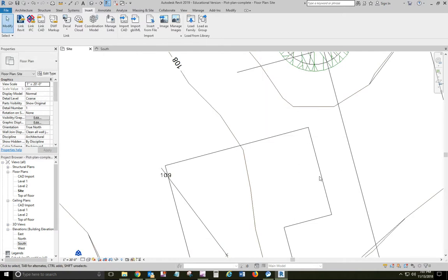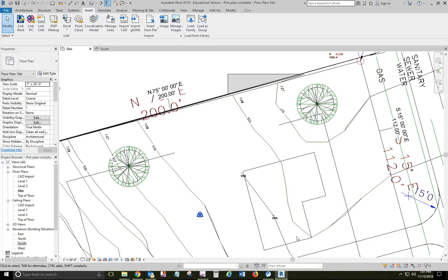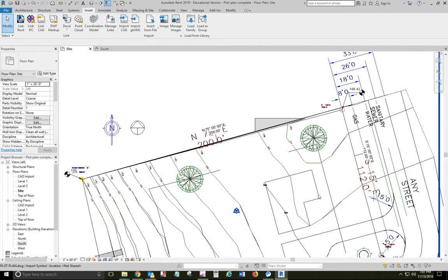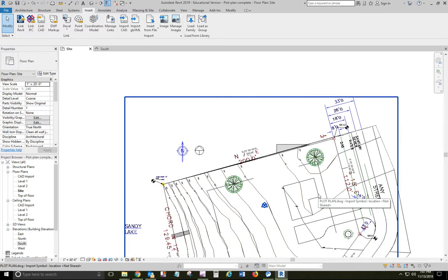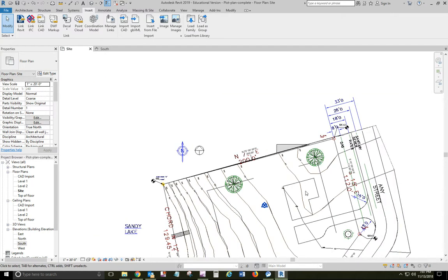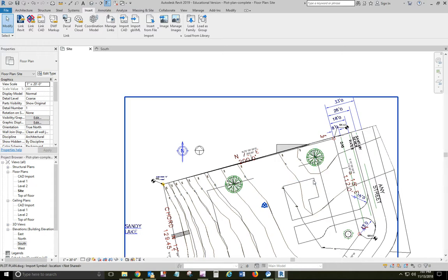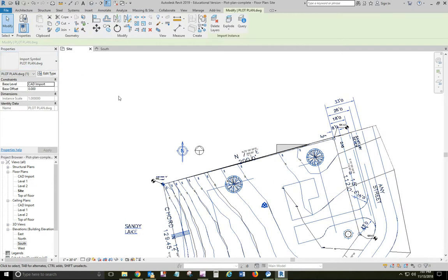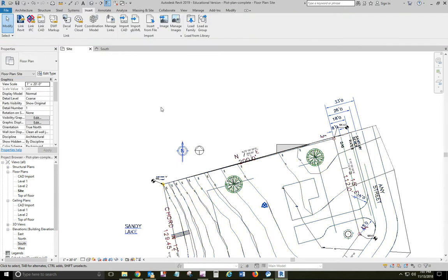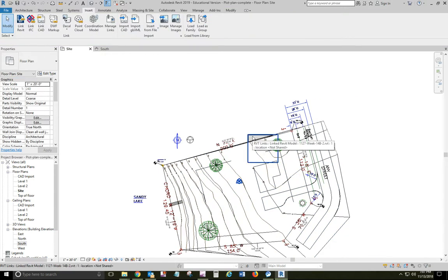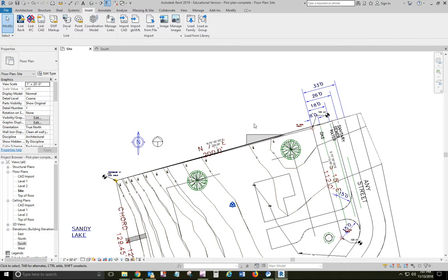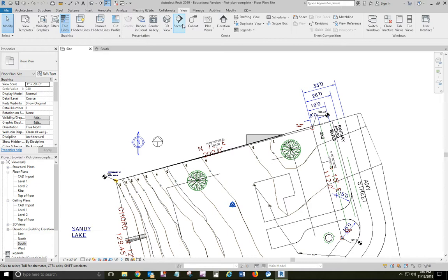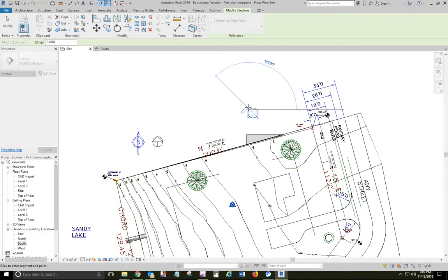of my building layout. This is the layout of the building that was in the CAD drawing. So if you're not seeing that, you just need to unhide or turn back on that CAD import drawing. All right, now you can see my building is right there. So to make this easier, let's pop a section view in that goes through the building and then through that area where I want the house at.